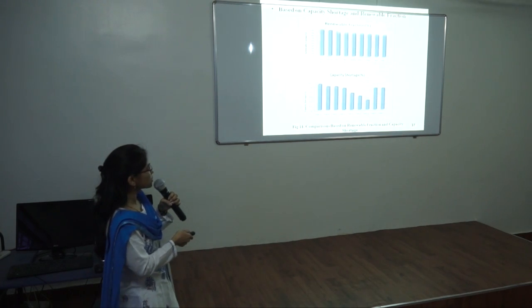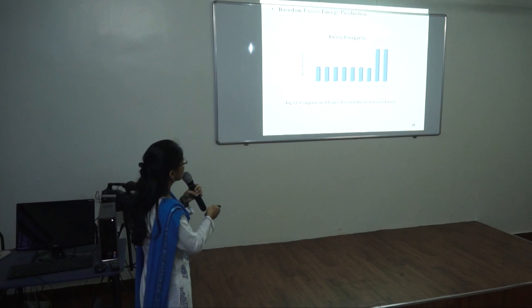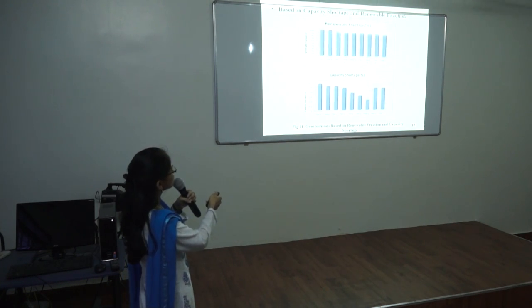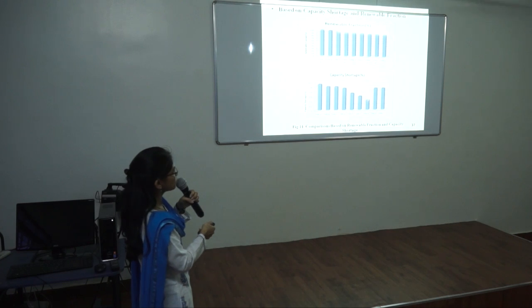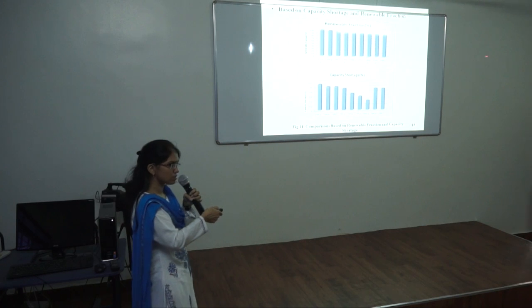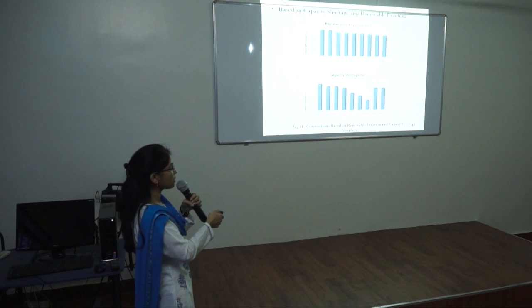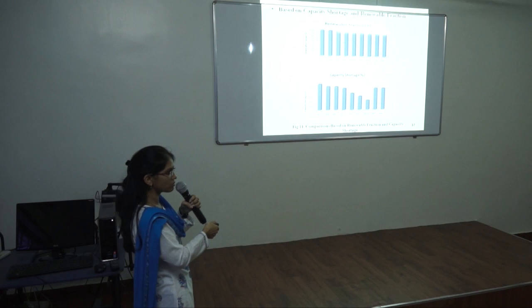The second comparison is based on capacity shortage and renewable fraction. By considering capacity shortage and renewable fraction as standard constraints, all types from A to I have a renewable fraction of 100%. Type G recorded a capacity shortage of below 90.4% with a renewable fraction of 100%, which is a good choice in this case. In comparing power systems with such constraints, the system with a higher renewable fraction and minimum capacity shortage is the good choice for reliable power supply.